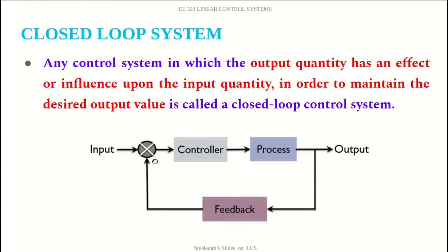Let's say that I've set the cleanliness of the dress to be 95%. Now it compares the cleanliness of the dress inside the washing machine, which let's say for the time being is 80% clean. That 80% gets compared with 95%, and since there is a difference, that difference is fed to a controller which converts it into the time for which the washing machine has to additionally run.